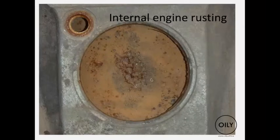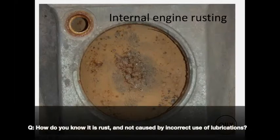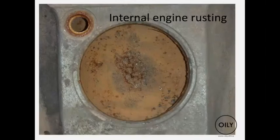Yeah, this is just looking through an inspection cover in an engine at rusting inside the engine. See, the outside of the engine's okay, but there was a plug here, and inside the engine you can see the rusting that's taking place. How do you know this rust is not caused by improper lubrication, but specifically cooling? Okay, that part of the engine was only running with coolant. There was no oil there at all. So only coolant was coming in contact there.